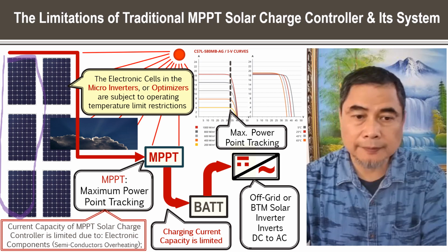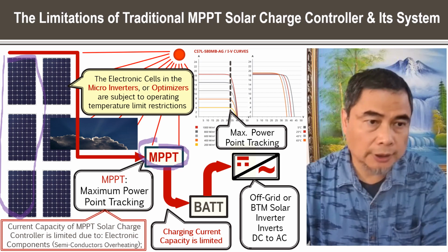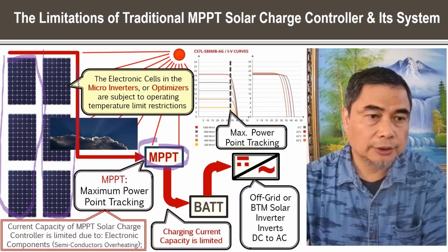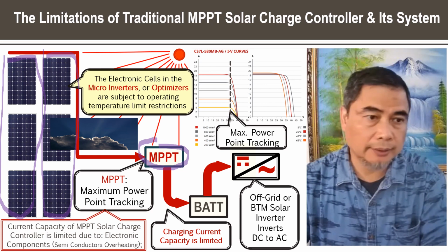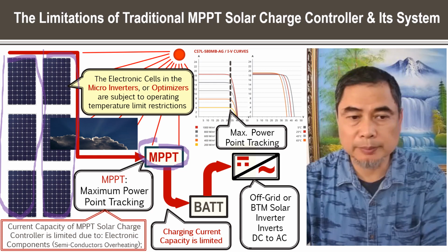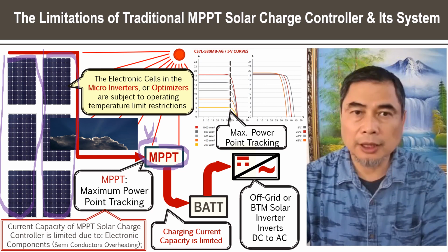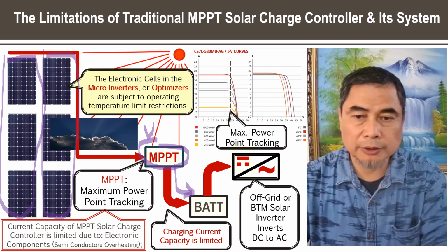If you have enough capacity on the MPPT solar charge controller, you may add another string here, to increase the input current as well. And the panels in series are limited by the maximum voltage you could have at the input side. The output of the MPPT solar charge controller is going to be connected to the battery port through the battery output.